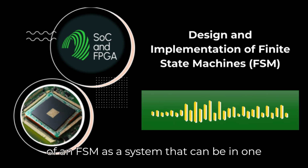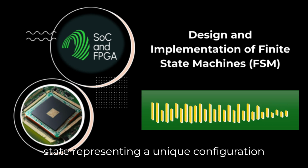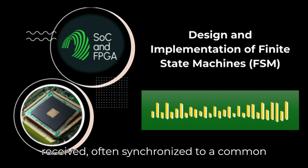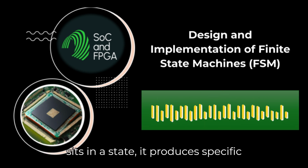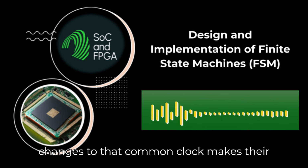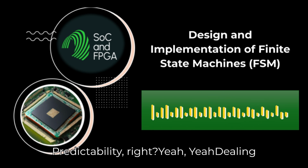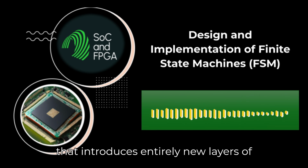That's spot on. Think of an FSM as a system that can be in one of several states at any given time, each state representing a unique configuration or memory of past events. It moves between these states, which we call transitions, when certain inputs are received, often synchronized to a common clock signal. And as it transitions or sits in a state, it produces specific outputs. We almost always design synchronous FSMs because tying all state changes to that common clock makes their behavior predictable, reliable, and frankly, much easier to debug. Predictability, right? Dealing with inputs that aren't synchronized or signals coming from different clocks introduces entirely new layers of complexity we'll get into later.